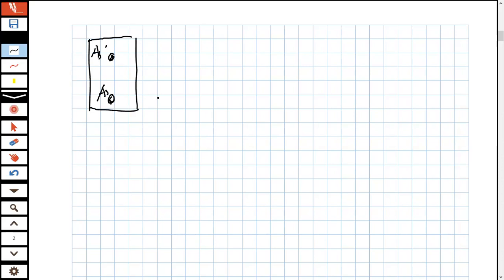First, we have this one generated by the tension reinforcement. Here is the C1, so it is easier to remember if you reinforce for tension first. And then this one is 0.85 f'c prime, and then you have here the width of the beam, which is b.